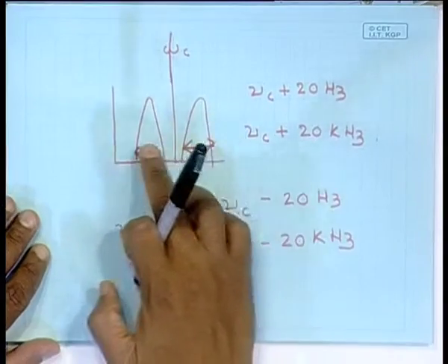No, because my voice spans the entire frequency range of 10 kilohertz. So, your radio receiver also has to be sensitive to the entire band, to one of the entire sidebands, to be able to reconstruct my voice from the signal that is being transmitted. So, the receiver itself has to receive the entire sideband. Both these sidebands contain the full voice signal.